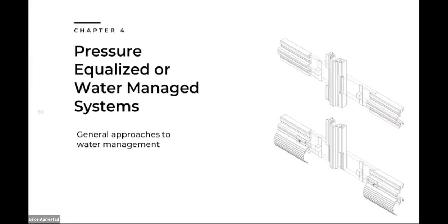That airtight inner barrier is on the interface of the wall behind the glazing pocket. And it must be sealed tightly to prevent air leakage. It ensures that pressure equalization happens only between the exterior and the glazing cavity, not through the building envelope. And then a fourth aspect to pressure equalized curtain walls is a drainage path. So here you're seeing that any water that does enter the cavity is directed out through weep holes or drainage channels. These are secondary defenses, since the primary goal is to prevent water entry in the first place.